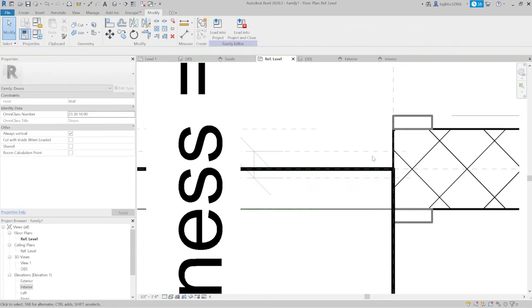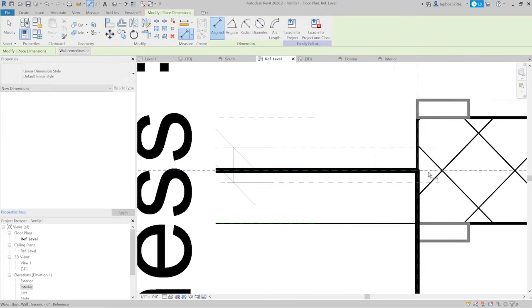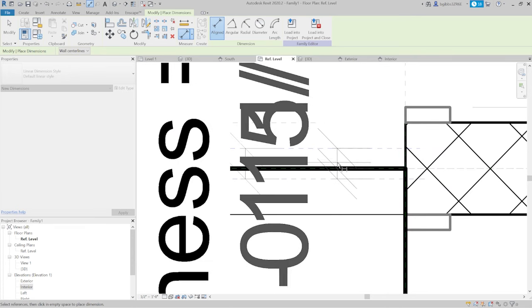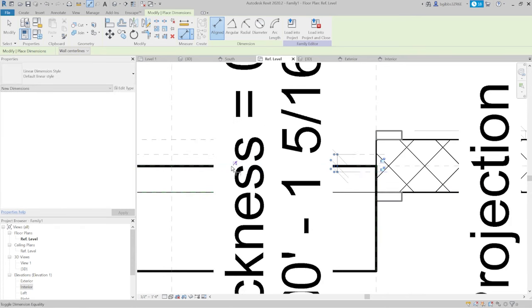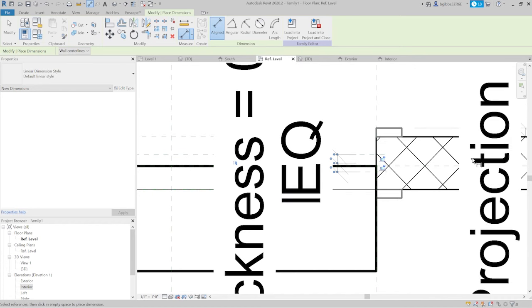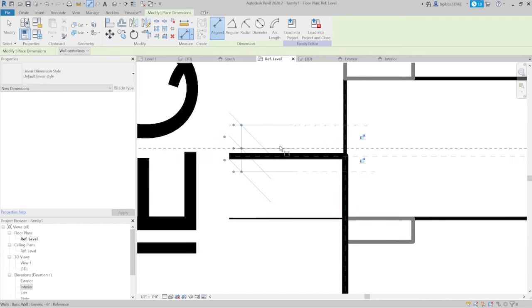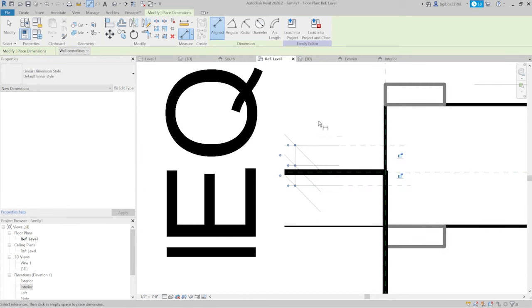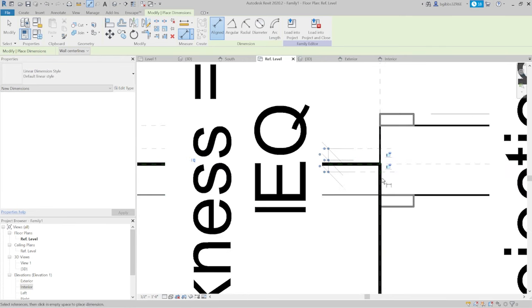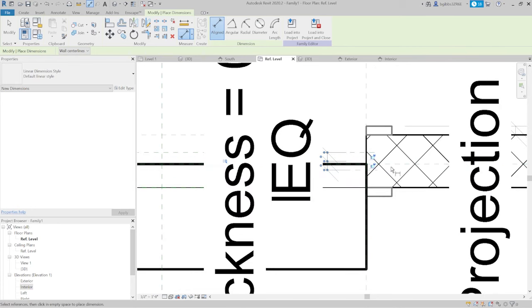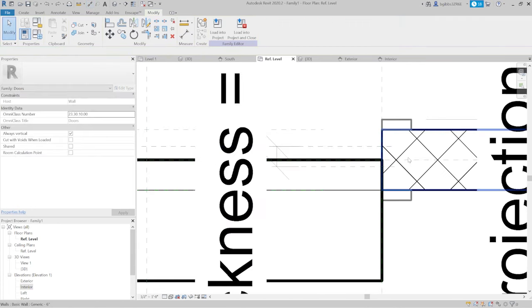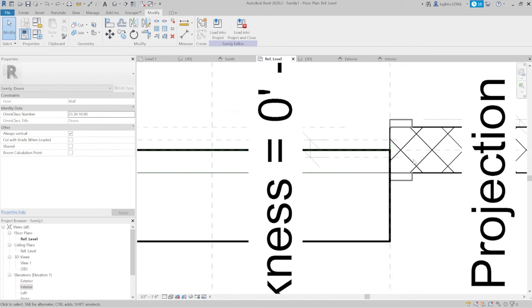And now to center it on this door line, which is the center of the wall, just making these 2 dimension strings, and I'm going to put equal to constrain them. Now, what would have been most useful is if this was started afterwards, because we've actually moved the wall. We don't want the wall to be moved. So let's try this another way.